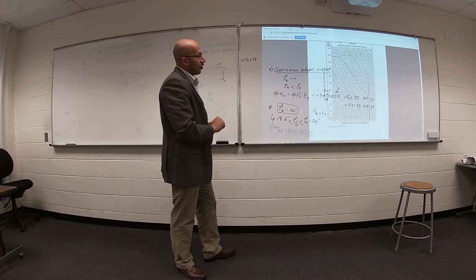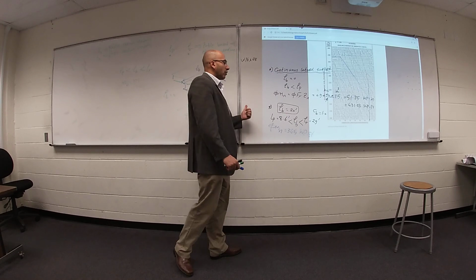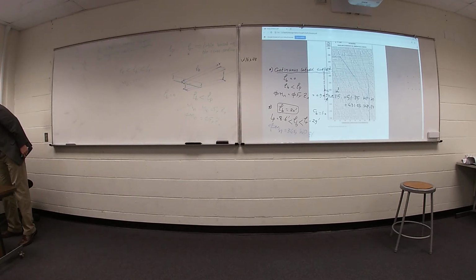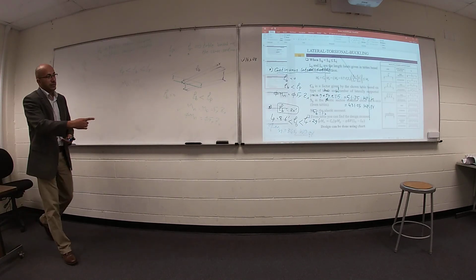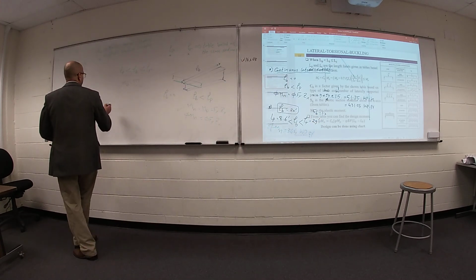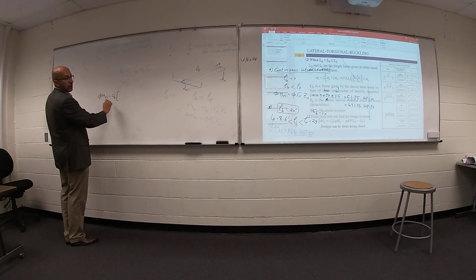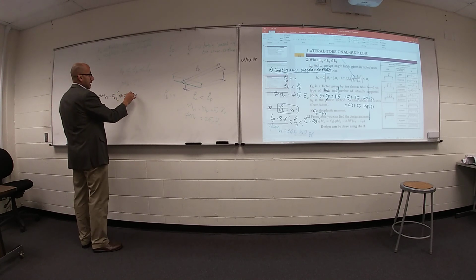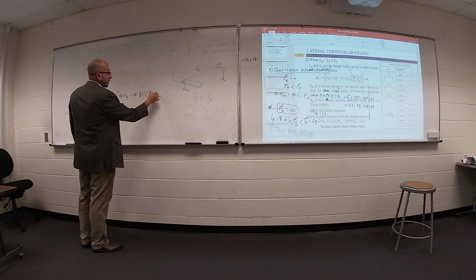If you did not find your cross section here, go ahead and use your equation. Let's try to use our equation. Let's start with this equation. Your design moment, phi Mn equals Cb times phi M plastic minus phi BF times LB minus LP.